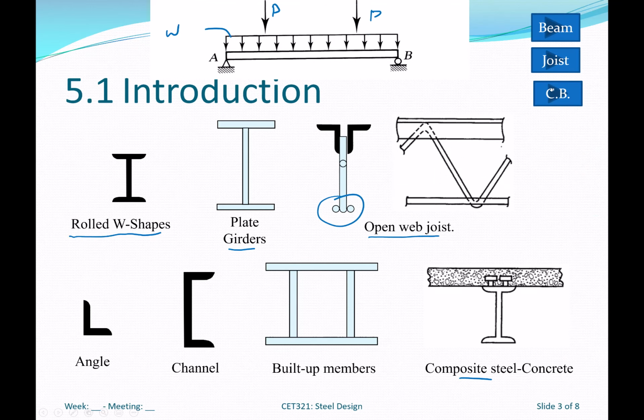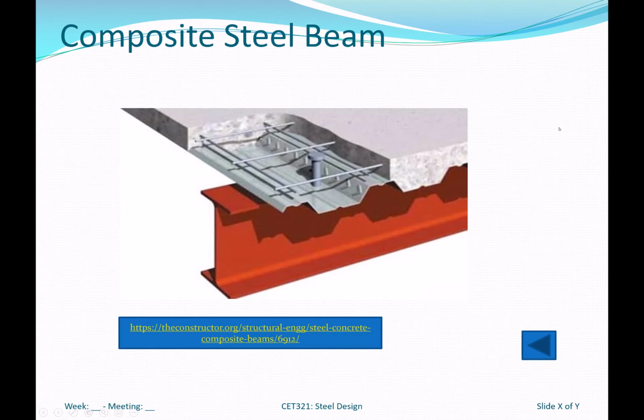All right. And then finally, composite joist or composite beams, right? There's this shear stud. Shear studs are welded through the metal deck, fastened to the top of the beam. So they place the deck on first, weld the shear stud on second, and place the concrete third. Once the concrete solidifies, it serves as the compression side of the beam. Real efficient use of material.